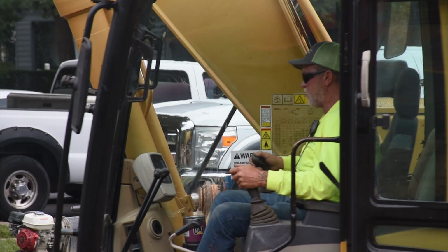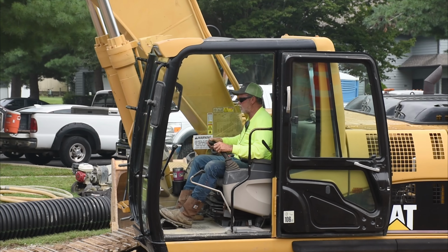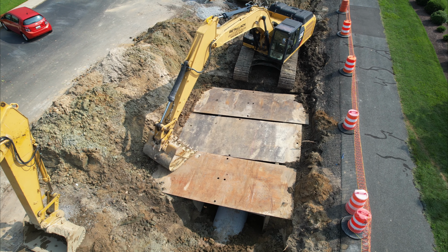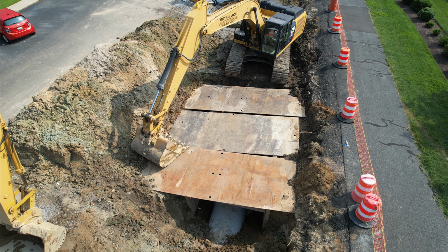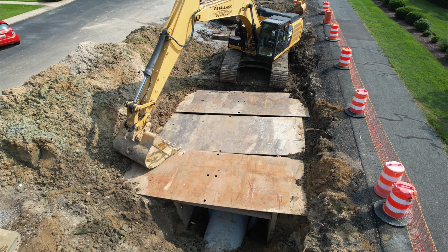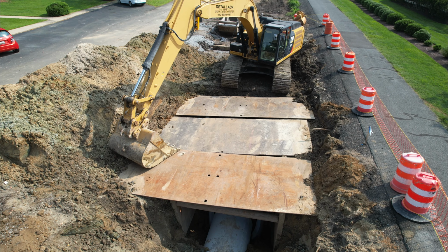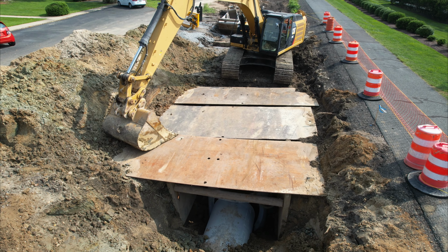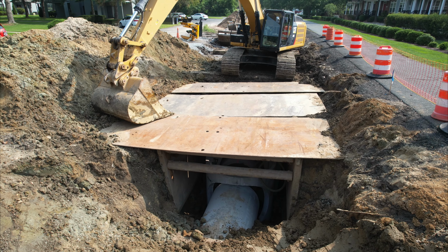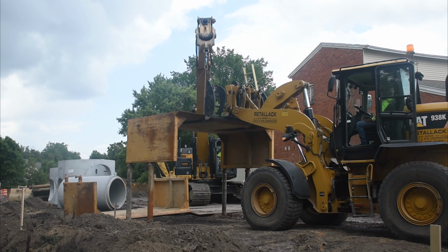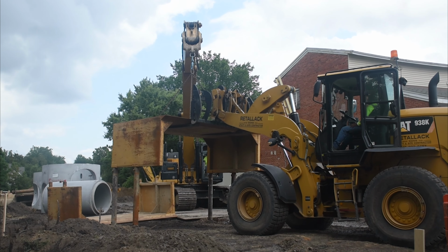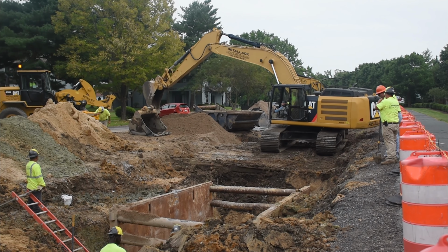As a fixed constraint, the sanitary sewer system ended up being a key driver of the new storm drain elevation. At the locations where the new storm drain crossed the sanitary sewer pipes, the sewer pipes were 5 to 6 feet below the surface. Combine that depth with the new storm drain pipes having an outside diameter of over 4.5 feet, and at a minimum separation distance, the new storm drain pipe is over 12 feet below the surface for much of its length.